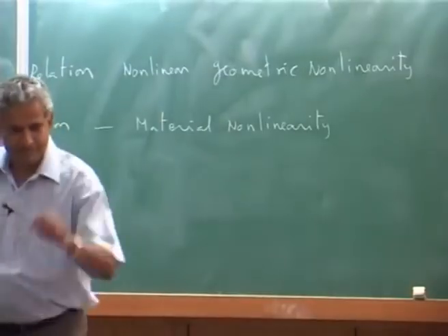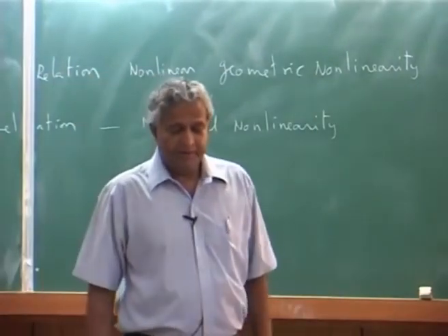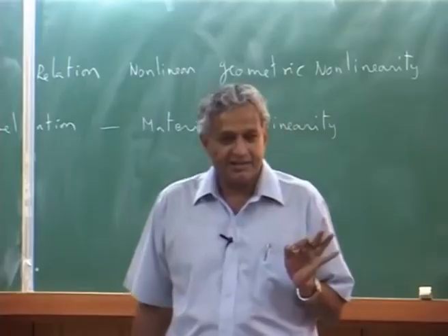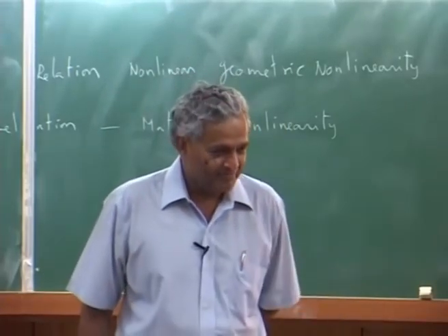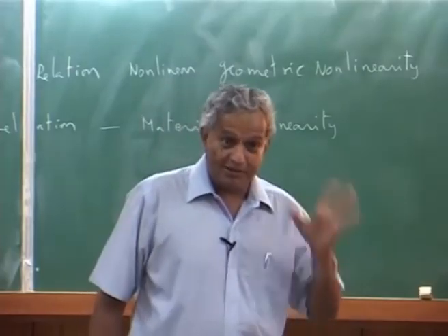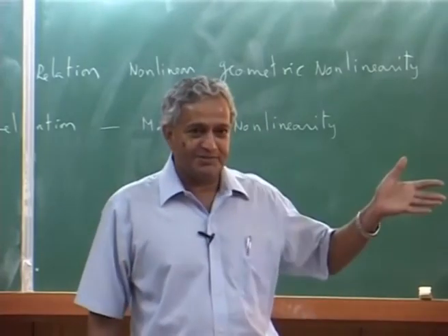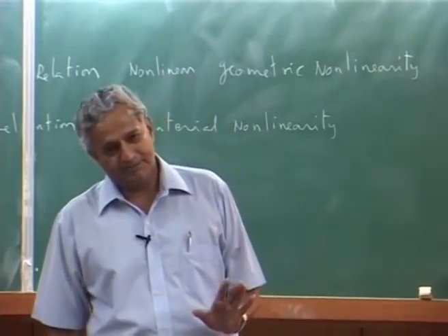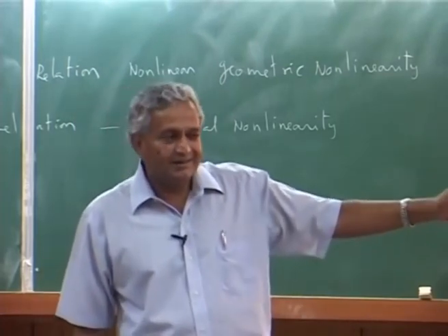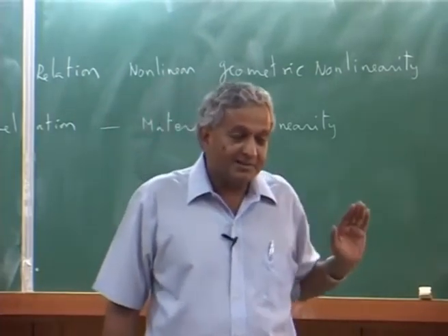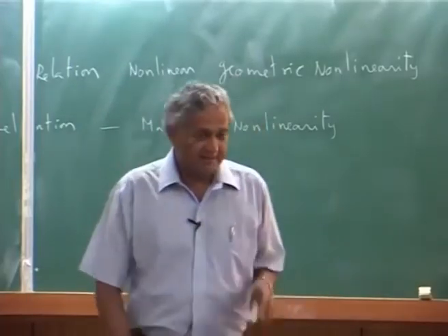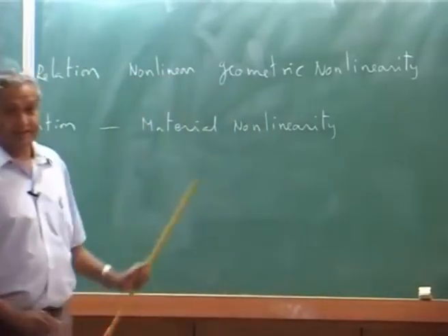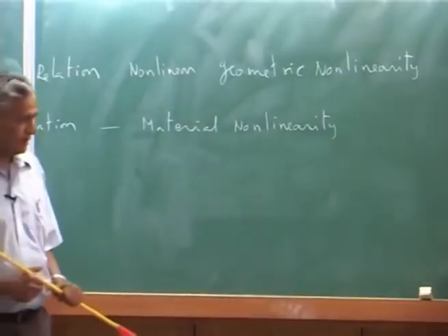The key is whenever you design a blade, you make sure that the strains are small, actually infinitesimal strain. Strain is small, but strain to displacement is not small, because the displacements, they do not say large, they say moderate deformation. It is not a small deformation. That is why this relationship is nonlinear.